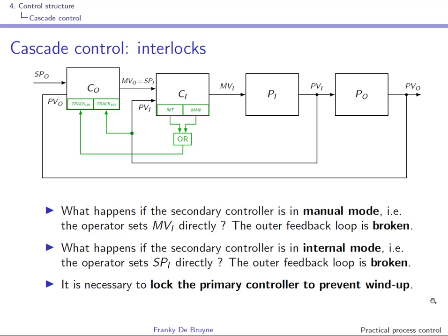Interlock problems due to a badly managed and implemented interlock strategy is the biggest source of problems in real-life situations. This is why vendors propose solutions to mitigate these problems. Some vendors propose a function block, an FB, implementing the master and slave controller with a correctly implemented interlock strategy. So you have one FB implementing the whole cascade.